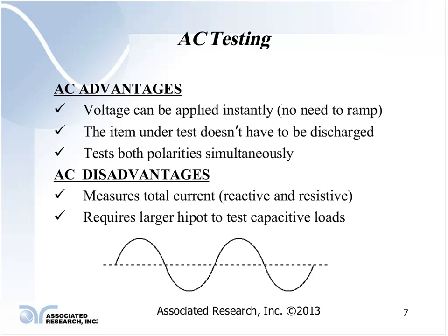Again, that is provided that the product is still connected at the end of the test. If you're doing what we call hot testing, where the probes are energized and you're moving from one component to another component just as fast as you can, energizing it, and then pulling the probe off while the Hipot is still on, then you may have to worry about the product holding a charge. Because if you remove that probe at the peak of the sine wave, that product will still be charged and could represent a shock hazard to the operator or the next person that comes in contact with that device.